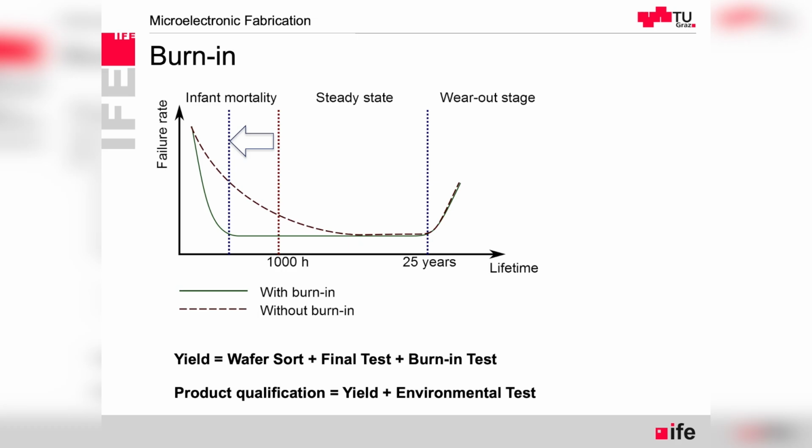And by doing this burn-in, that means putting the chips in the oven and operating them for some hours, we can reproduce all the failures that will happen in the first several hours, and then we avoid having shipped them to the customer, and then the customer complaining that maybe 1% of the chips that you have delivered are returned, saying that something went wrong and it doesn't work.